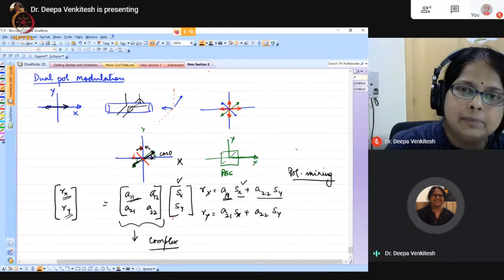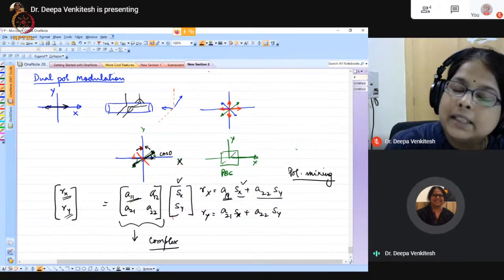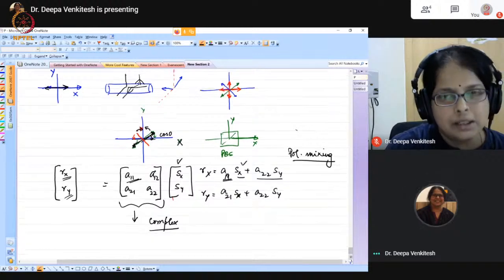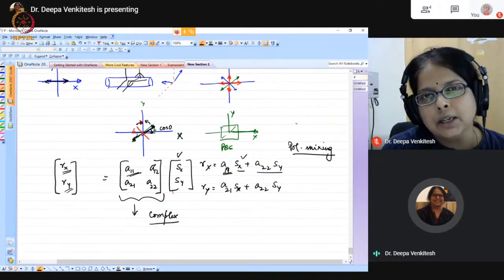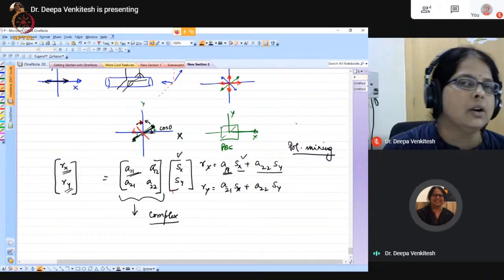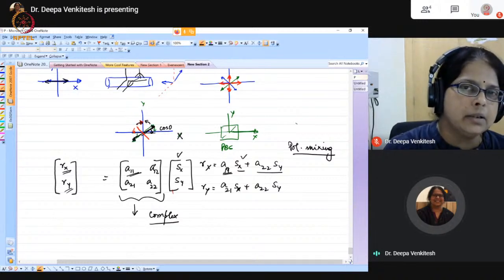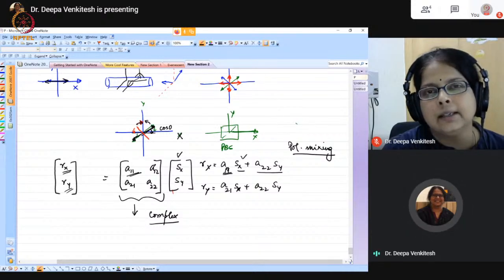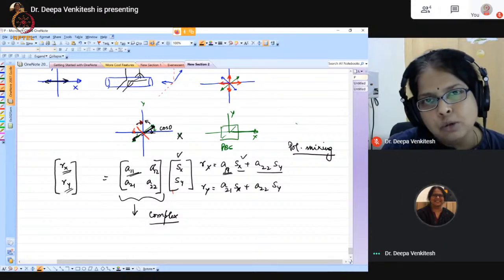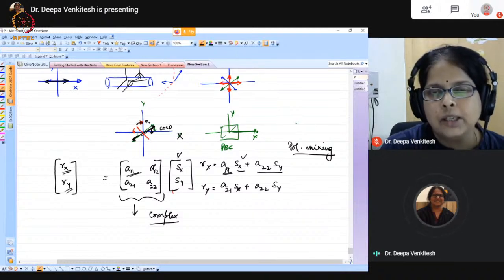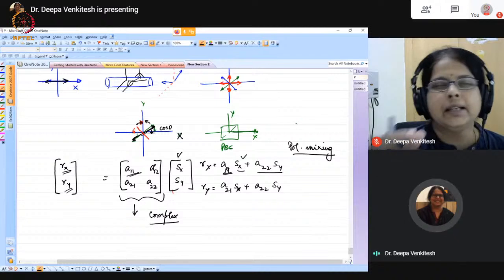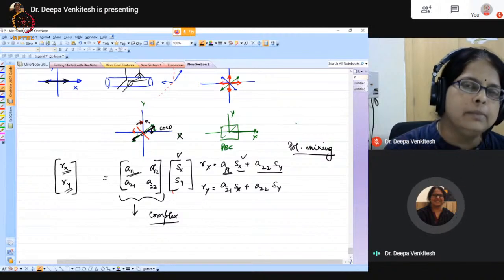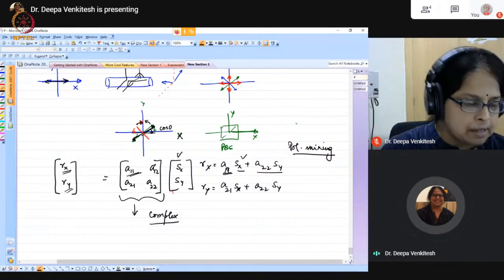But the problem is that the polarization mixing or the polarization dispersion is a statistical quantity. It is not a fixed phase delay. Unlike chromatic dispersion, which is more or less a constant, this polarization dispersion, the walk-off between the X and Y polarization, is not a constant. It is a statistically changing number, so it becomes somewhat hard to correct for this impairment. So the best way is to avoid it. You make sure that the delay because of polarization dispersion is much smaller when compared to the bit slot, so that your bits are not dispersed because of polarization dispersion.